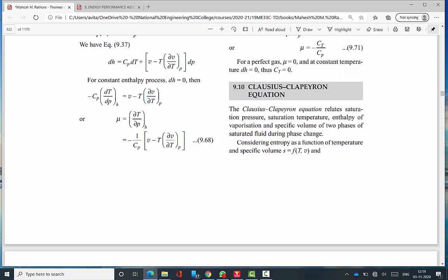For example, for water the freezing point is 0 degrees Celsius. If we have 1 liter of water and put it in the freezer, the temperature of the water continuously decreases up to 0 degrees Celsius. Beyond that, the temperature doesn't change until all the water is converted into ice. This duration is called the phase change duration. During that phase change, temperature remains constant. Then once all the liquid is converted to ice, the temperature drops.